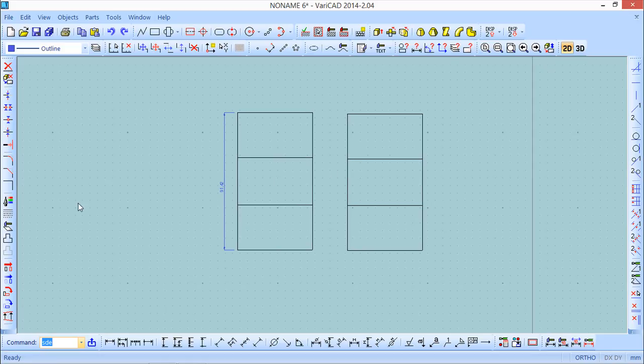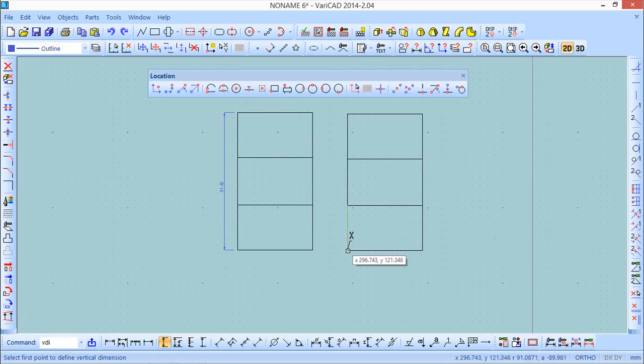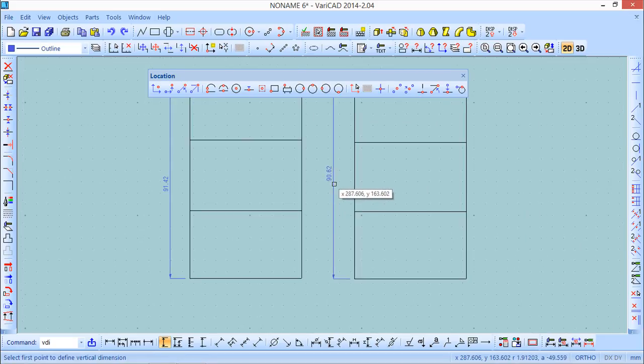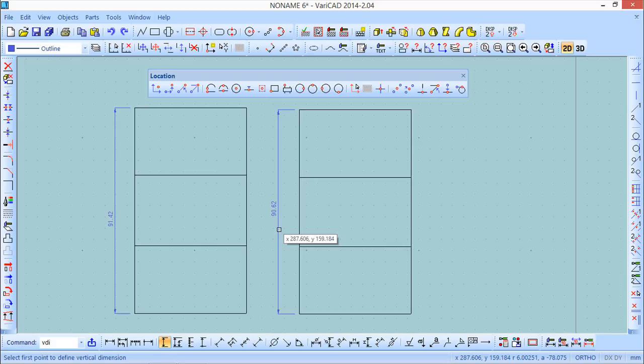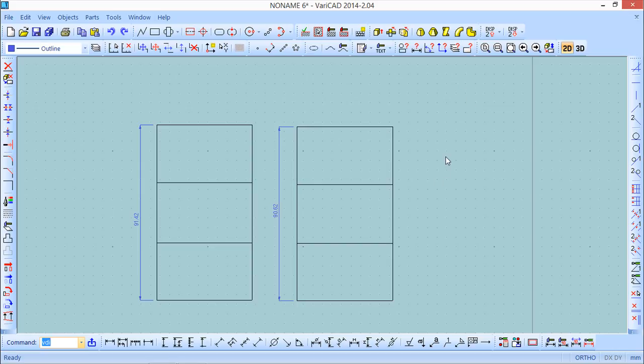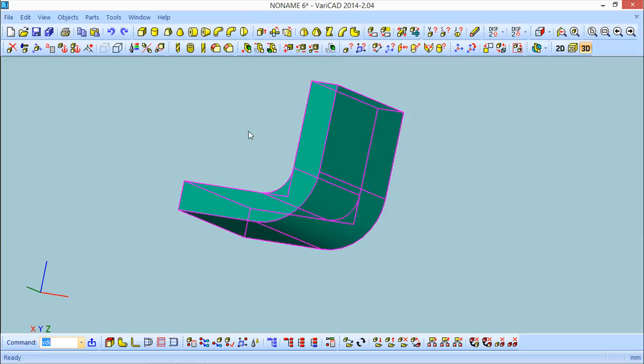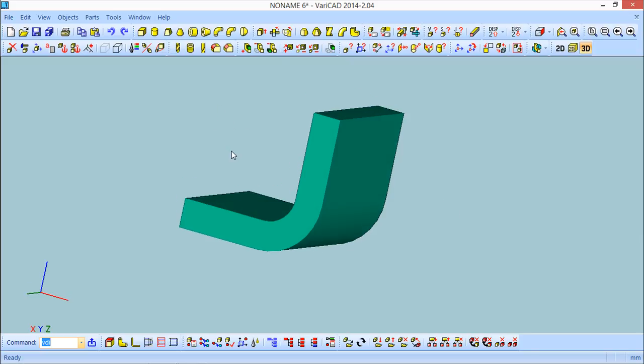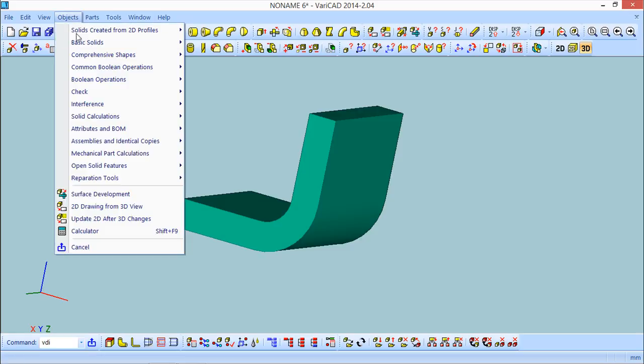Probably you see no big difference, but if you put the dimension, you see you have a difference, because this unbend of round areas has some math behind, so it is important to get the right thickness on the sheet metal that is going to be used.